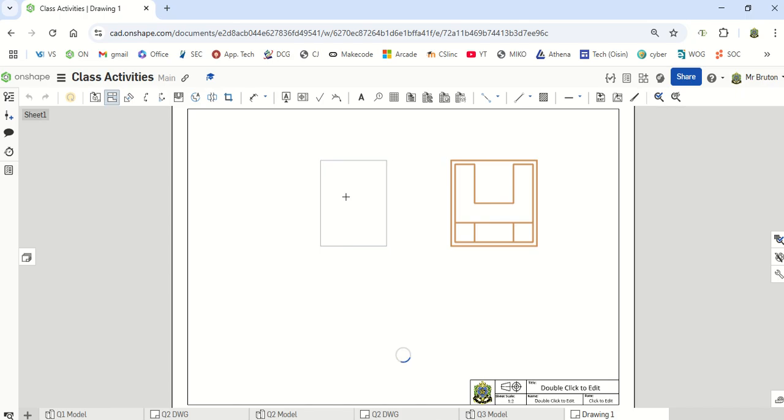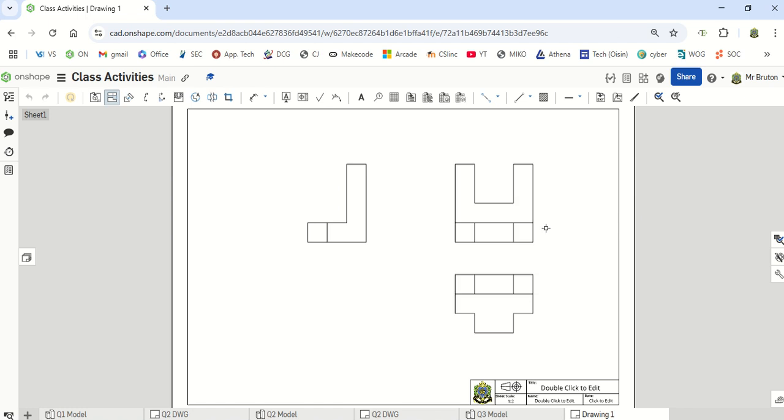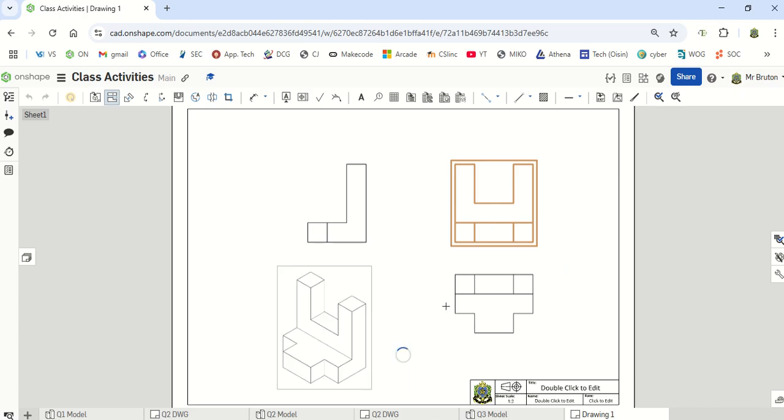We draw the side view on the left, and then we go back and we always put our plan underneath the elevation. Lastly, I want to do my 3D view, so come down diagonally. And again, I want to show hide. Turn that off.